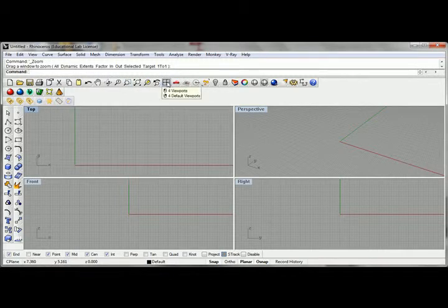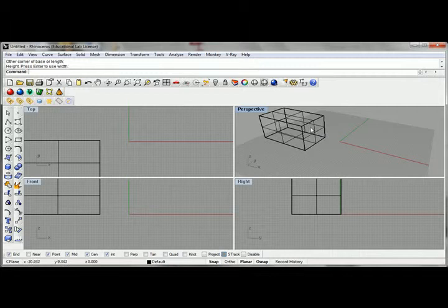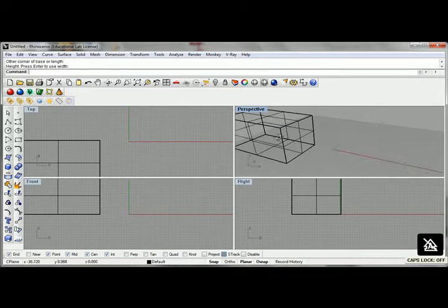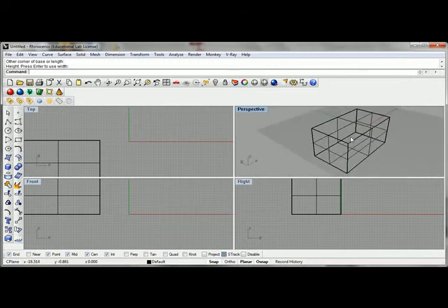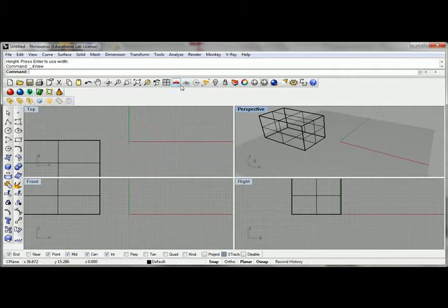Rhino has a weird tendency to, if you position an object and rotate around it consistently, shift around and constantly orient over that, and it saves that orientation, and sometimes it gets stuck or the camera starts to lock up. You can reset that by just clicking that button and resetting it. Setting views, setting construction planes, things like that. You shouldn't really have to get into that until you get into some more advanced functionality.